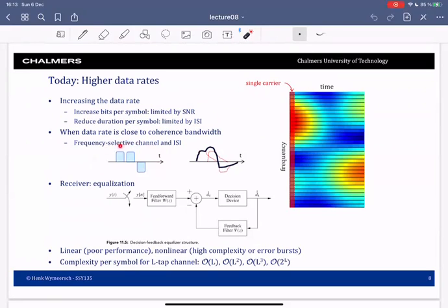So this is what is shown here. At the transmitter, I have these distinct pulses, 3 distinct pulses, but if these pulses are too short, they will blur together here, leading to intersymbol interference. Good. How you would deal with intersymbol interference, there are different ways.